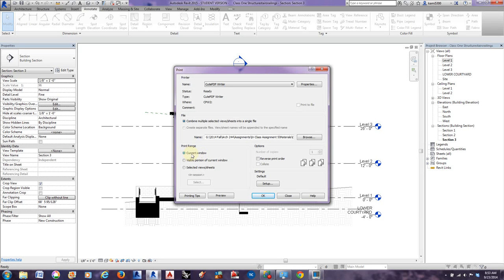and what that would do is basically print the entire viewport. So if you have other elements in the viewport, it's going to want to associate that with the print view, and it's going to make your print view giant. Sometimes what you actually want printed will be off the page because you've got multiple objects in the same viewport.